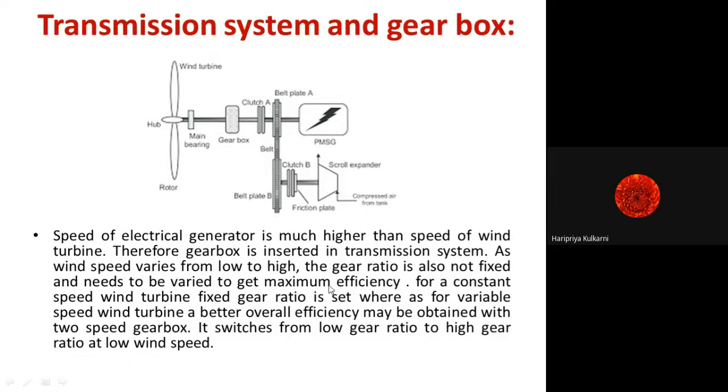So why are we doing this? Generally, depending upon the geographical location, we acquire the wind speed. If the wind speed is less but more than, let us say, 5 meters per second, then surely we can generate energy from the wind. We can extract the energy from the wind, and depending upon the gear ratio, we can increase the speed. By increasing the speed, we can run the PMSG, permanent magnet synchronous generator, so that we can use the electrical energy at the output and accordingly utilize it.